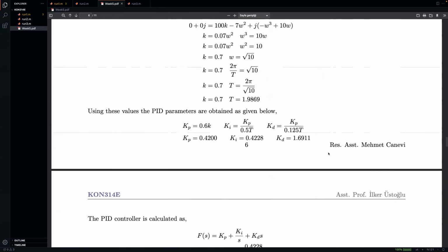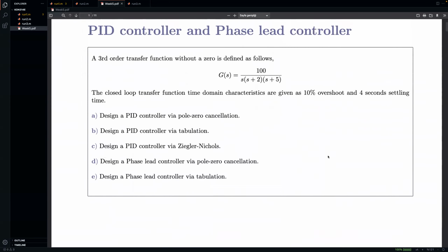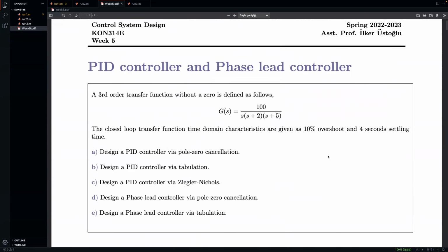We've talked about the PID controller in more depth, as you can see, and we've also talked about the phase lead controller. If we're designing a phase lag controller, most of the time the design will end up having an infinite amount of solutions because, well, we don't want to touch the transients that much. And therefore, in time domain, when we design a phase lag controller, what we do is we just choose the origin, and near the origin, we add a pole and a zero, so that in terms of root locus, the difference of the angle contribution is not that big.